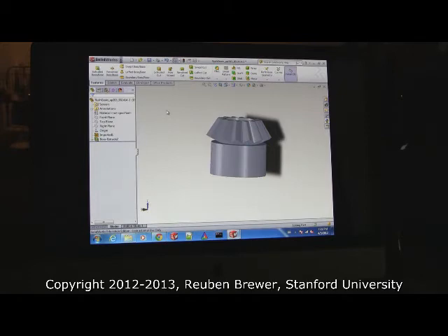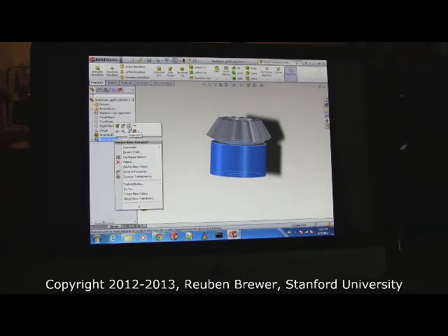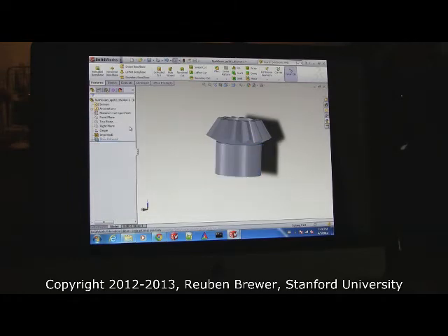Real quick, if you don't want to delete something, but you want to basically roll it back, right-click, and you see this little thing here, suppress. It goes away. See how it's blanked out here? Now we right-click, unsuppress. This is a double-edged sword. You have to use it sometimes, but beware, it's dangerous. If you have a bunch of stuff after that, and you hit suppress in the middle, it suppresses everything beneath it. It's a parent-child relationship. When you then unsuppress the thing you just suppressed, it doesn't unsuppress all of the children. So then you're going to be clicking one by one. Just be careful.